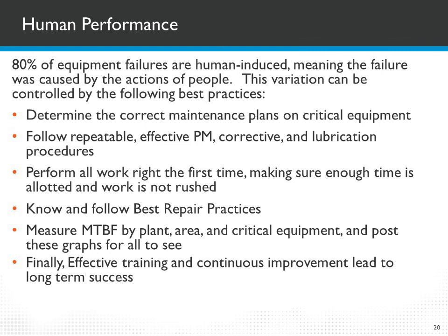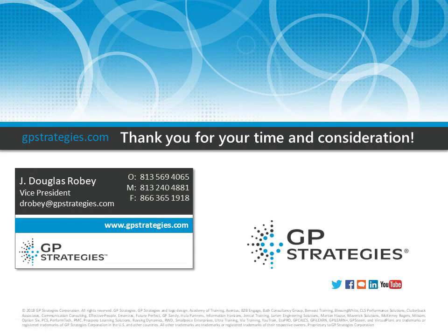Looking at some of these slides, did you have any examples of where any of this applied to one of our clients or customers? A good example that I can come up with is we worked with a steel company that had a bearing issue. They were going through over $4 million a year in bearing cost. By doing the proper assessment up front, it was concluded that they were misaligning equipment and installing bearings incorrectly. This was due to the fact that they had improper procedures in place and their mechanics were not trained properly on coupling, shaft alignment, and bearing installations.